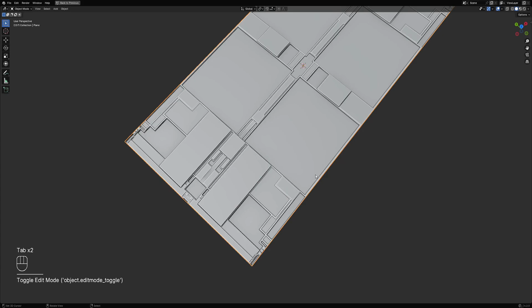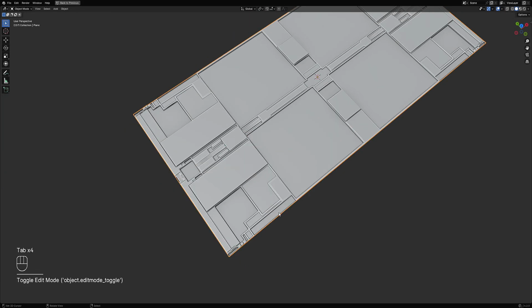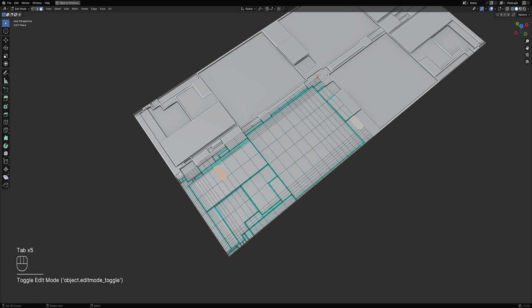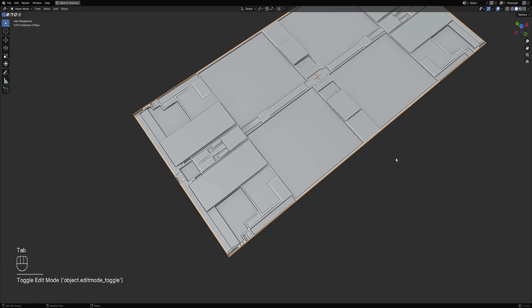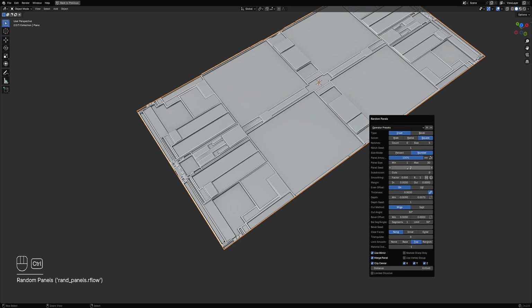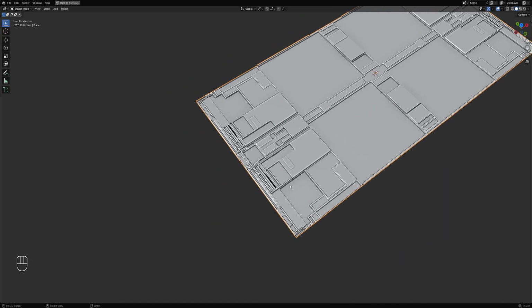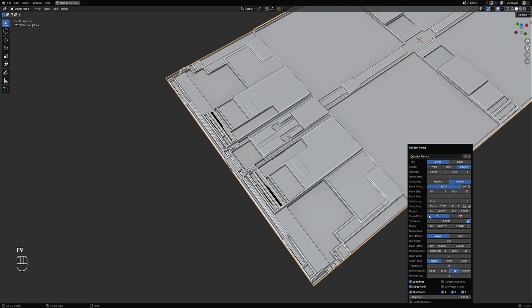So for example, here, and here, and here, press Alt and then click on the operator, and we increase the subdivision. These are overlaps. We need to fix some of the properties, like the thickness, to avoid the overlap.